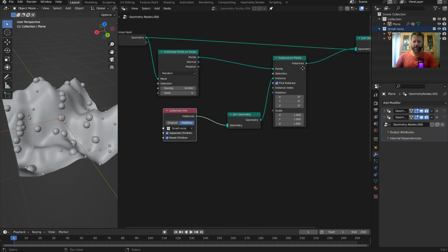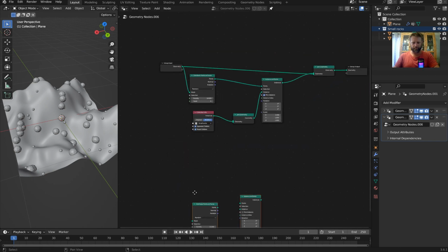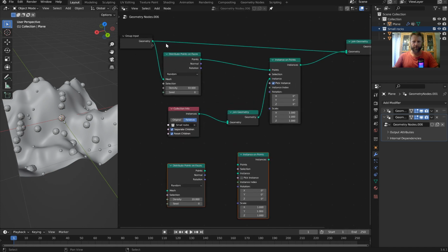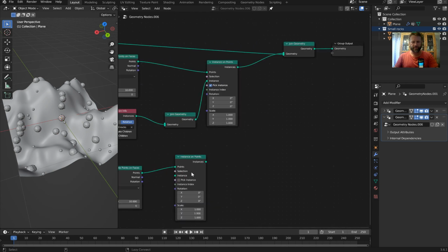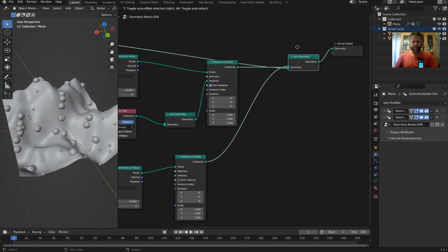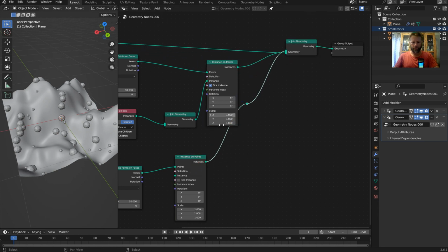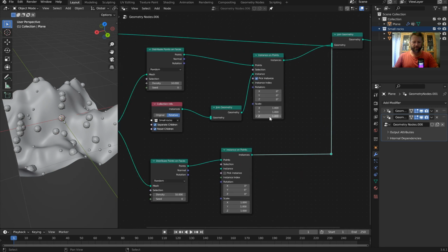So we can go ahead and bring up our other node group. I'm going to shift and right click here, and I want to bring this little reroute down, and I'm going to tag in the instance on points, and then tag this into the join geometry and just add another reroute. I want to keep everything nice and clean and then create another save point.